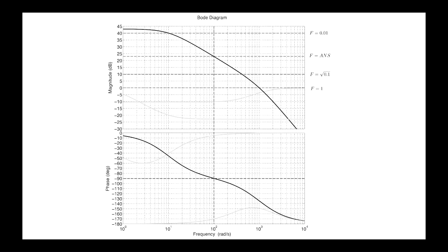So in the case where there's no compensator, just the resistor divider network, rather than figuring out how different values of F pull the magnitude plot of the op-amp transfer function down, because we're multiplying by a number that's less than 1, you can think in terms of how varying F just changes where the 0 dB line is, right? Moving the 0 dB line up is the same as moving the other plot down, right?